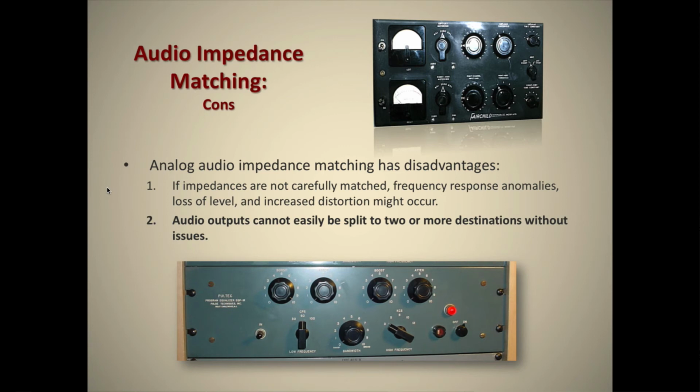They followed the telephone company system. And this is cool, and it works fine until there are any anomalies, any real issues with matching the output of your Pultec and plugging it into your Fairchild. You start getting changes in level, and you start seeing potential distortion and potential frequency response issues.